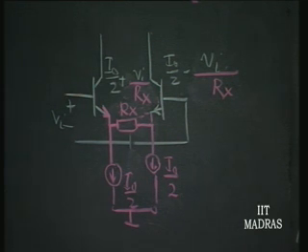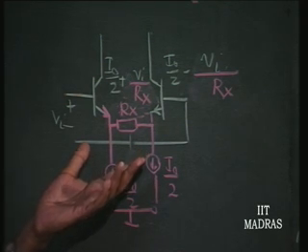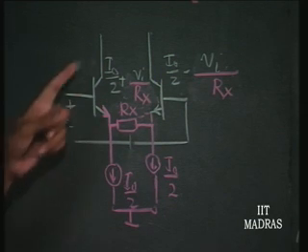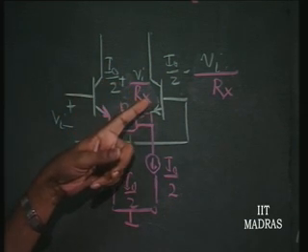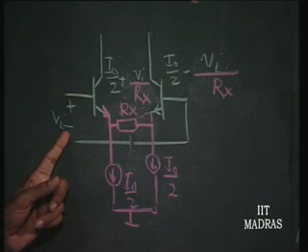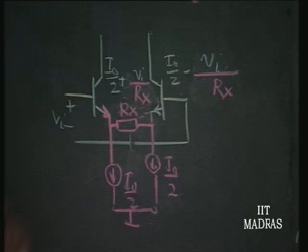Right. So, this is again a differential arrangement where whatever differential voltage is applied here, corresponding to that only the signal current will be coming. If you have a common mode voltage here, there will be no signal current here. So, this is the strategy adopted, that is, you have equal current sources, and now this can be used for negative feedback mode of operation, etc.